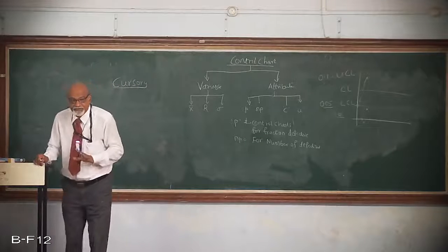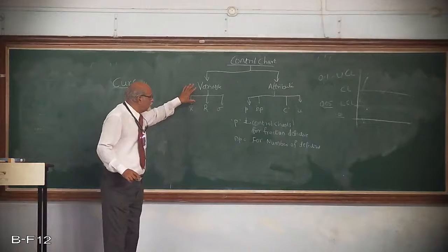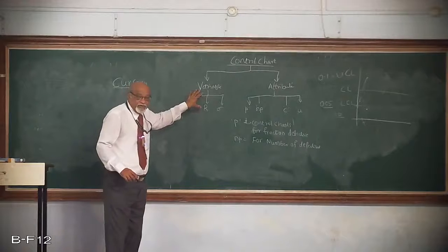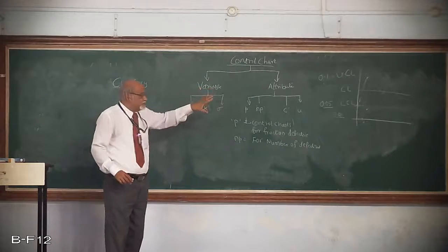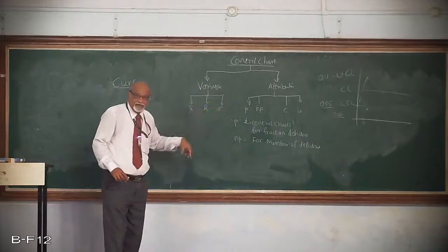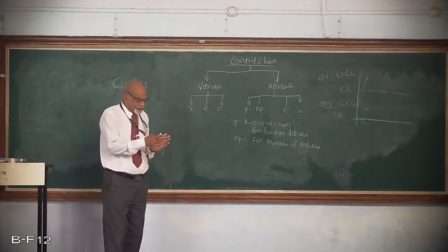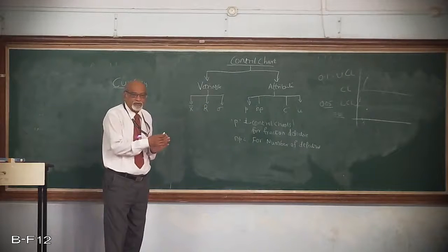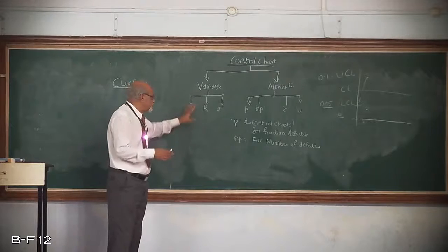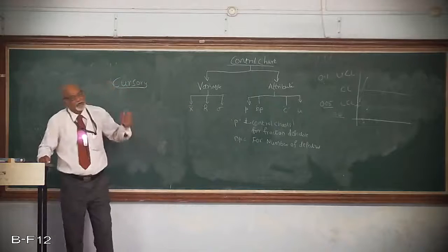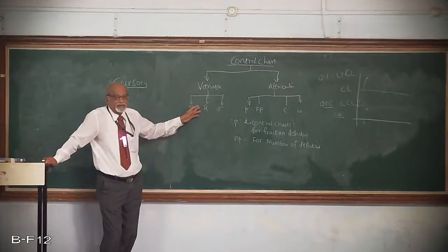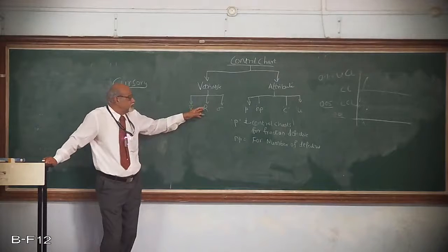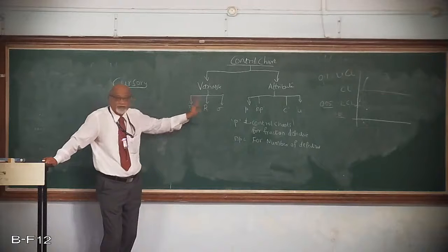That means when I should go for a control chart for variables and when for a control chart for attributes, because there are 4 types. When I decide to go for a control chart for variables, then the X bar chart is to be used. Then, depending upon the available data, I can use it in conjunction with R or sigma.